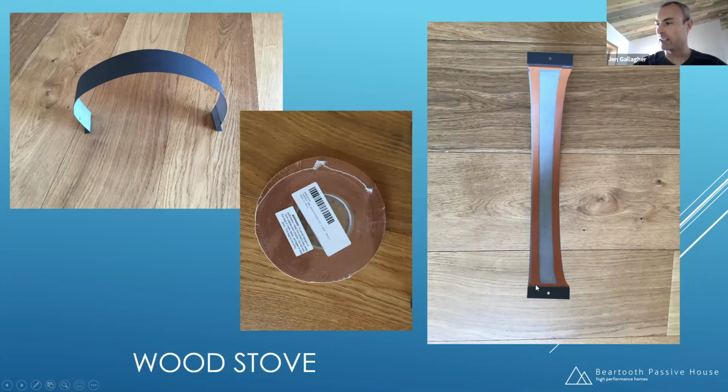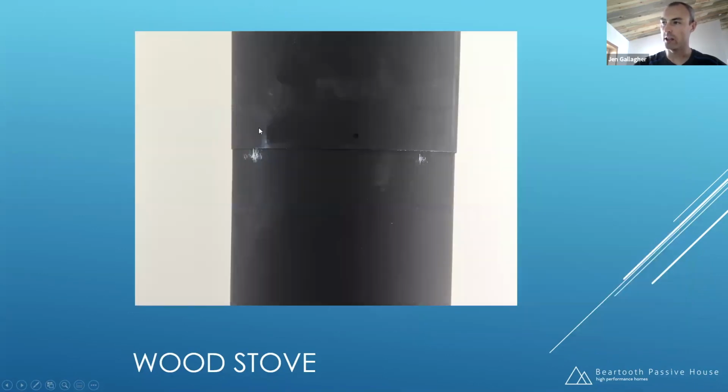So what I did is I put 2 strips on the top and bottom of this collar, so that when I took that collar and wrapped it around this joint, the top seal would hit the top part of the telescoping joint, and the bottom seal would seal against this bottom part of the telescoping joint, and it was just held together with a screw.